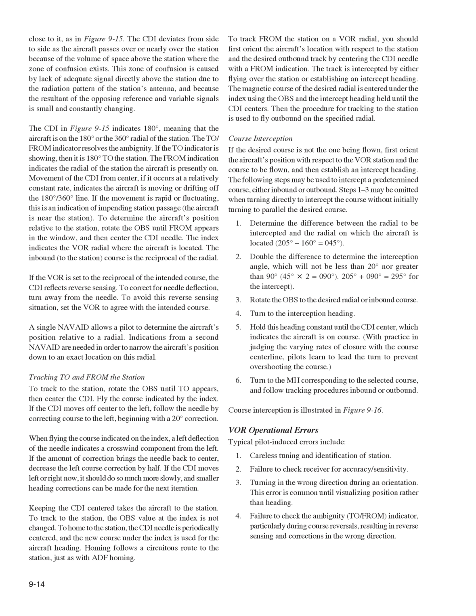205 degrees plus 090 degrees equals 295 degrees for the intercept. 3. Rotate the OBS to the desired radial or inbound course. 4. Turn to the interception heading. 5. Hold this heading constant until the CDI centers, which indicates the